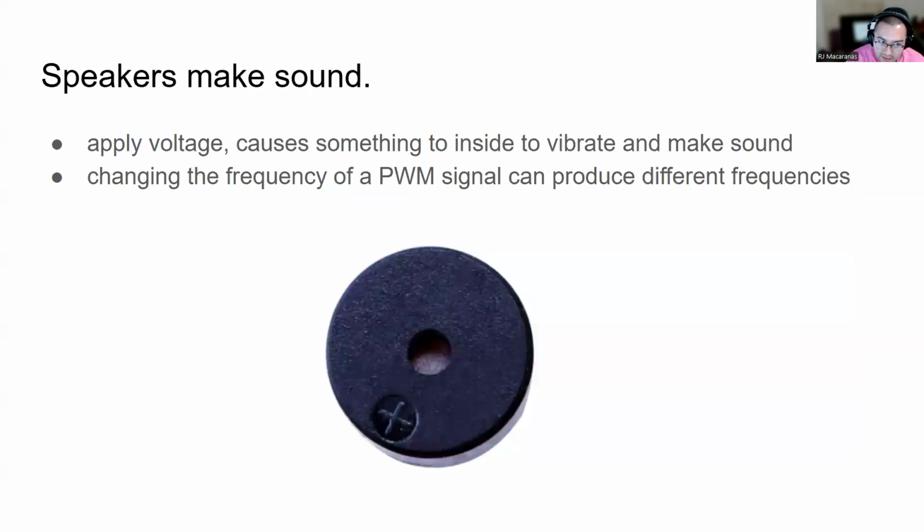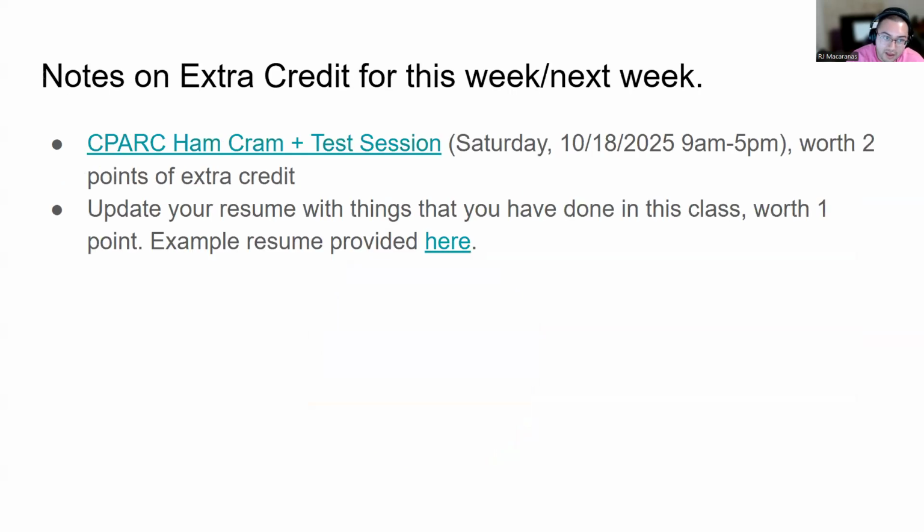Now getting into how we realize the sound. We've got speakers in our kit. There's this little passive buzzer, and we can control the frequency of a PWM pin in order to drive this little speaker and make different frequencies of noise.